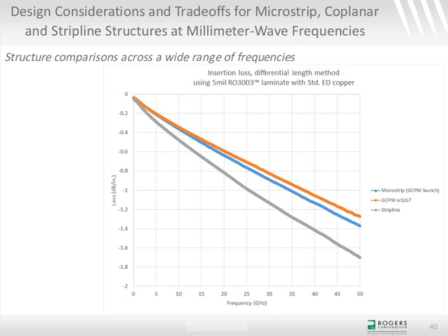I hate to say it depends, but it does depend. So if you have a high dielectric constant material, then the coupling between the lines is different than with a lower dielectric constant material. Personally, I would go with a substrate thickness relationship myself. But, man, that really does depend on the dielectric constant, because that can alter the coupling a lot.